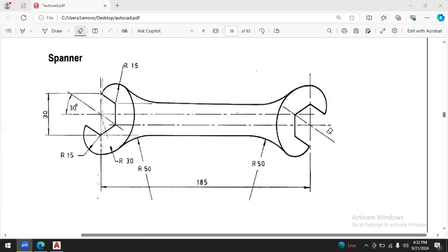If you wanted to go for the mirror command, you certainly can, but it will take you more than a single step. So it is better, if you want to copy, to use the rotate command. So let's begin with that next approach.